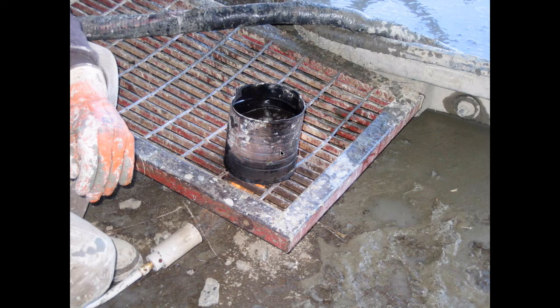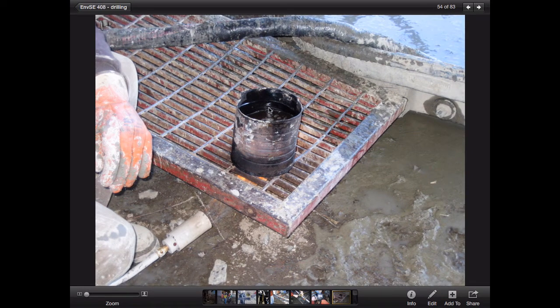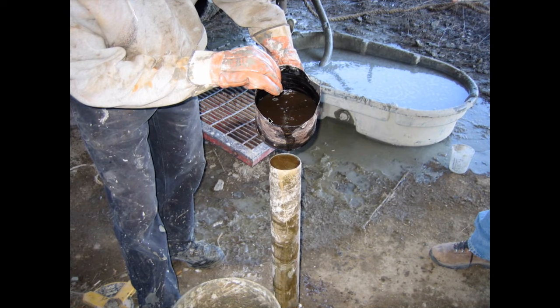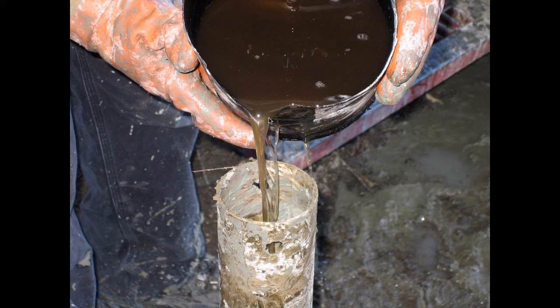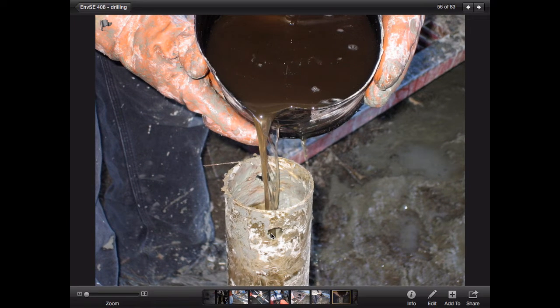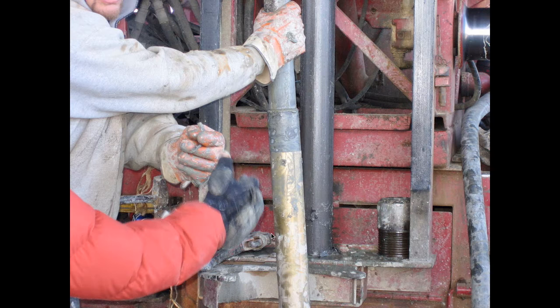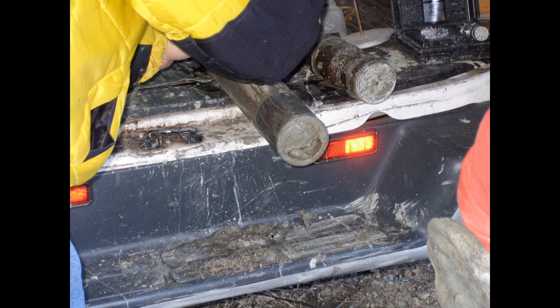And once you have the sample, a typical way of sealing it is to cut some of the clay off so you have a bit of freeboard, melt some wax with a tiger torch. This is molten wax, and then pour it into the top of the tube and seal the moisture in, and take the undisturbed sample back to the lab to do whatever you need to do with. These are the holes that go onto this assemblage. So put some end caps on it, put some labels on it, and you see what this is. So this is just the process.